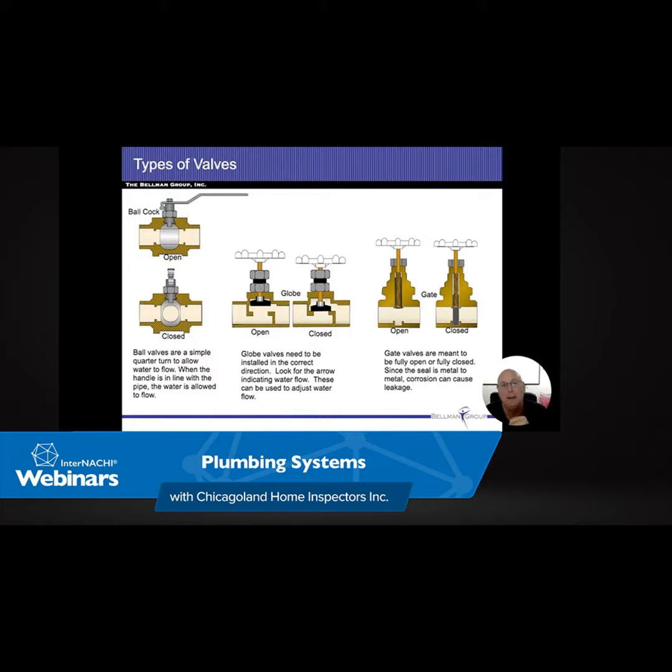So if the well has a steel liner or some sort of casing on it so that it's not open, versus the dug wells I was talking about before where they had stones stacked around them: if it's that type of well, then it has to be 100 feet away from the septic system. Obviously, it's easy for the wastewater to flow over and get in there. But if there is a liner or a casing on it, then you could be within 50 feet.